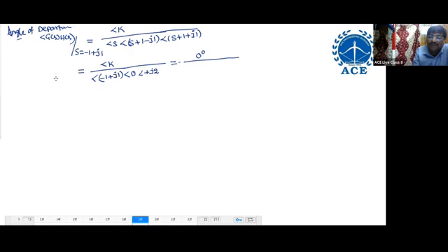Angle of minus 1 plus j1. Minus 1 means negative real axis, plus j1 means positive imaginary. That means second quadrant. What is the angle for the second quadrant? 180 minus tan inverse of imaginary part by real part. So use 180 minus tan inverse of, what is the imaginary part, 1, what is the real part, 1. So this is the angle. Plus 0 degrees, plus j2 means 90 degrees. Now tell, what is the answer? tan inverse of 1 is 45, 180 minus 45 means 135 degrees.